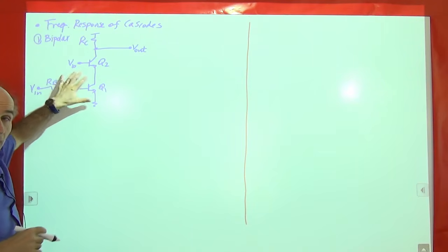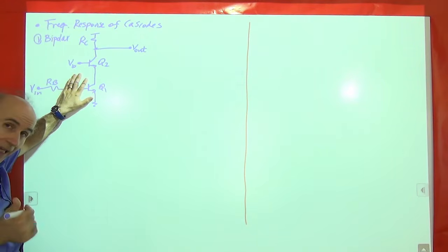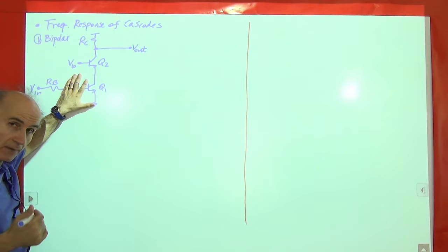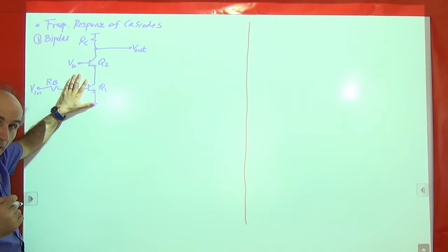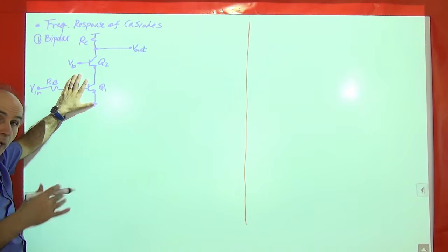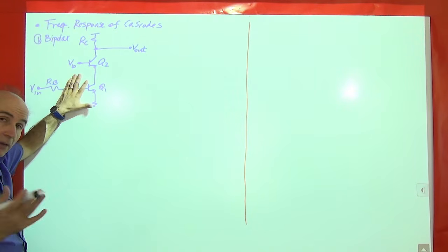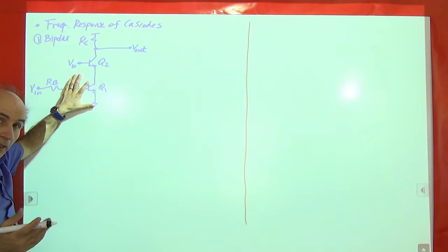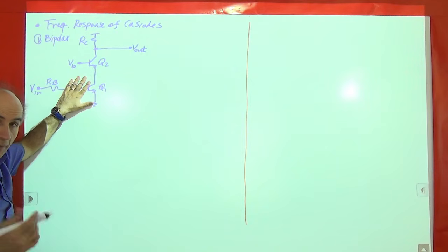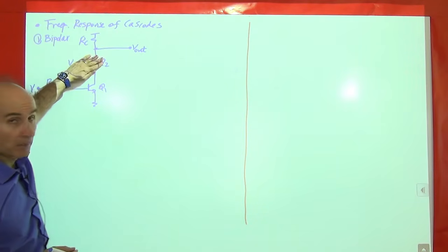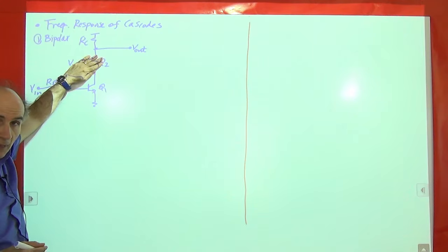All right, so we like the cascode topology because it provides a higher gain and a higher output impedance. But it also has another beautiful property, discovered well before these things, in the 1930s, maybe 40s, in conjunction with the Miller effect. What we will see is that the cascode topology has less Miller multiplication than the non-cascode topology, meaning just the basic common emitter stage.